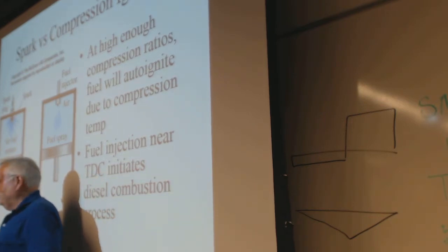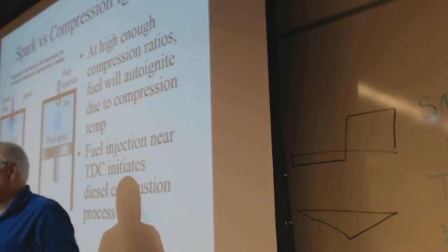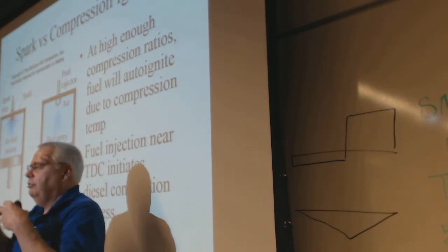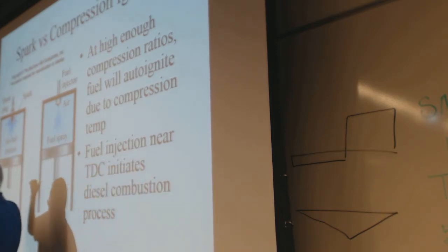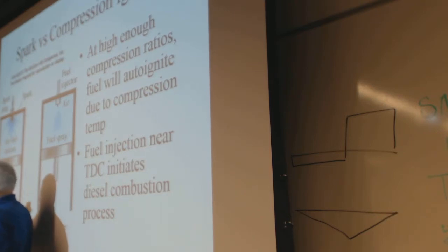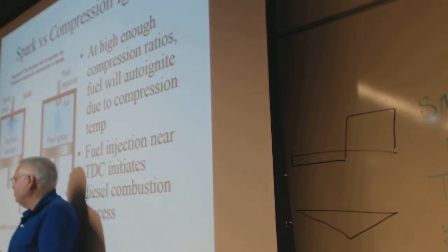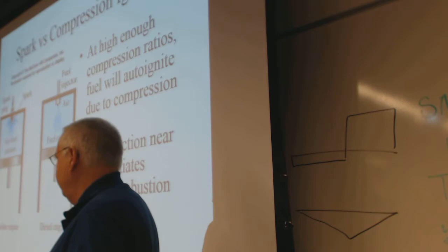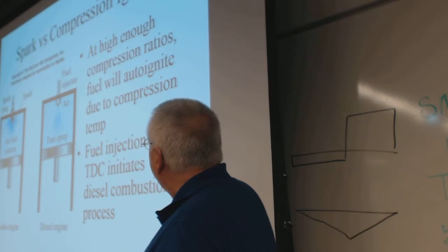So they denature it, they poison it with gasoline, which also makes it possible for it to cold start. Because if you get 15% gasoline in there, then the gasoline will vaporize enough to start, and then it warms up. And so we see E85 is the maximum ethanol, 85% ethanol, 15% gasoline. There's the flow flood thing, and there's the fuel start issues that you have, especially with the renewable, with ethanol, the gasoline renewables.